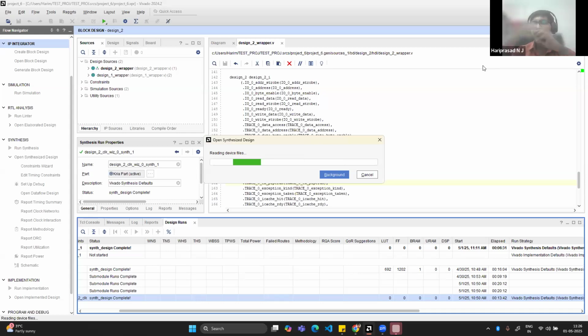Defense applications are the worst case. Defense and SATCOM are almost similar, but in SATCOM we also have to consider radiation tolerance, because along with the temperature, in space there is a lot of radiation. As you understand, every bit matters in an FPGA. If in one complete FPGA one bit is corrupted, the whole circuitry will spoil, right? So there they use a technique called the scrubbing mechanism, where they keep refreshing the switches every time. They also use parallel mechanisms, so if one chain fails, they go for another chain.